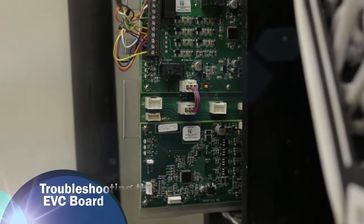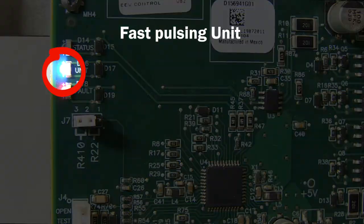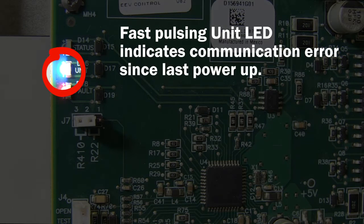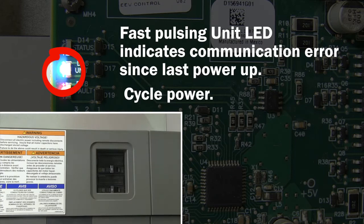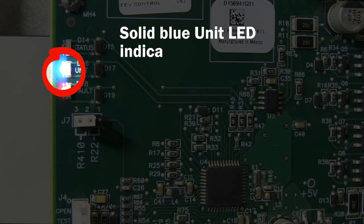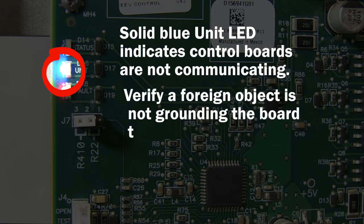Troubleshooting the EVC board. If the blue unit LED displays a fast pulse, a communication fault occurred since the last power-up. To see if the problem persists, cycle power to the unit. If the blue unit LED is now solid, the boards are not communicating. First, verify that a screw or other object has not fallen behind the board, grounding it to the chassis.